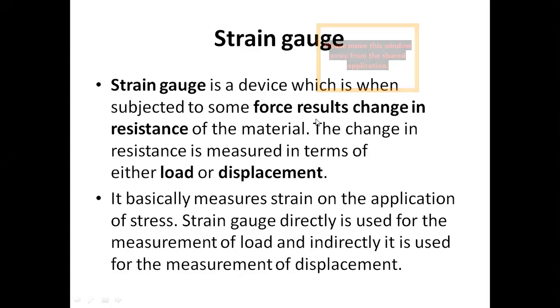So today's topic is the strain gauge. We already saw strain gauge in the second unit, so anyway, we'll be recollecting all the things that we already know. When we talk about a strain gauge, it is actually an electrical transducer, and it is used to measure mechanical surface tension. At the same time, it can detect and convert force or small mechanical displacement into electrical signals.